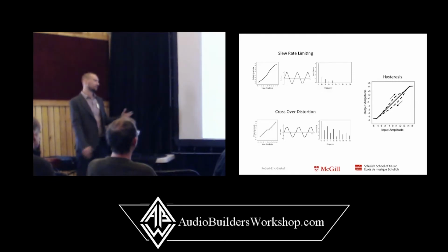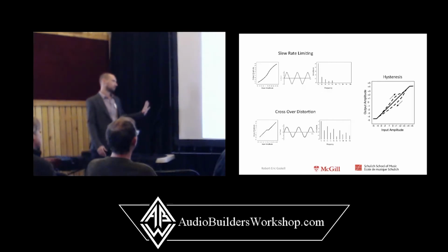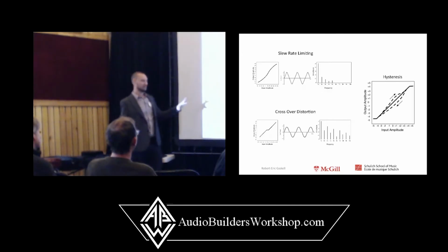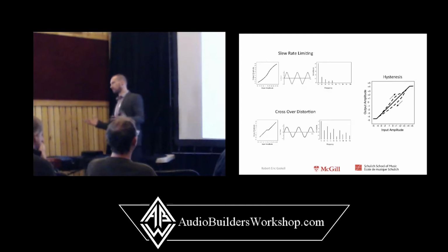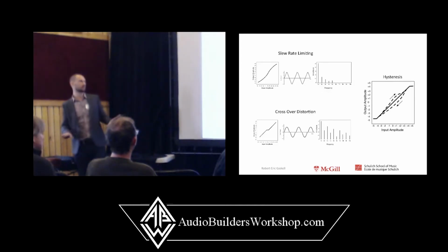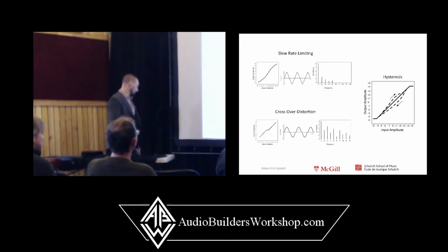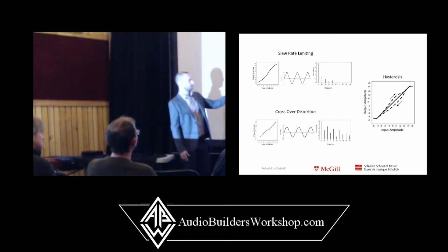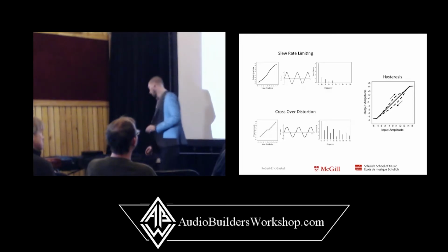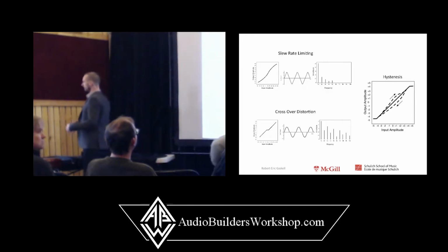We also have crossover distortion, which for small signal audio electronics really is not a significant factor. Because of feedback, we can linearize this effect, and typically crossover distortion, even in op amps with push-pull output stages, is not a concern, is not really a contributing factor.